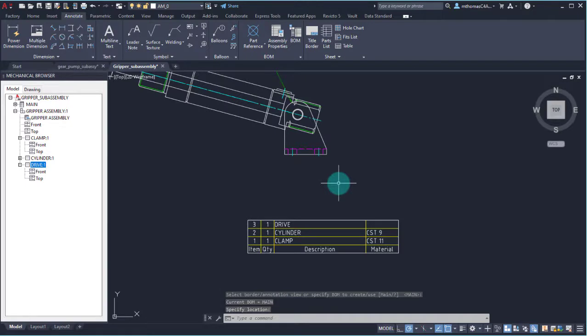So you can see that structure is a way of adding these kind of smart block-like groups to lines, arcs, circles, and other shapes, and then have this structure where you have these parts in their views, and you can start building these assemblies of components. So that's how you can use AutoCAD Mechanical Structure to define bill of materials and parts lists and then balloon your components.